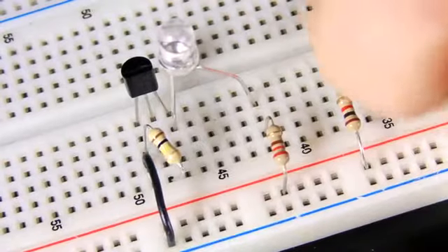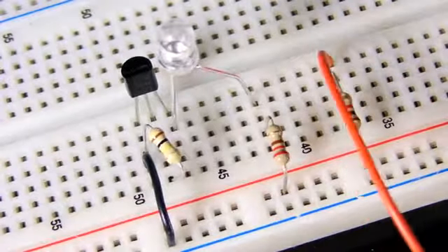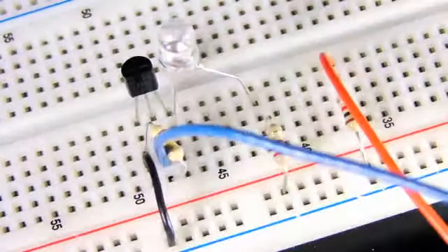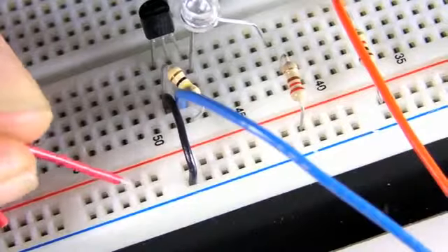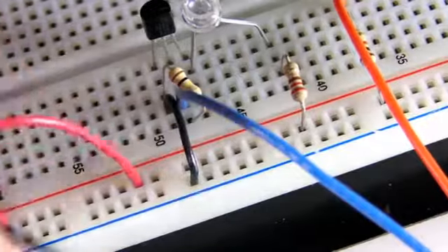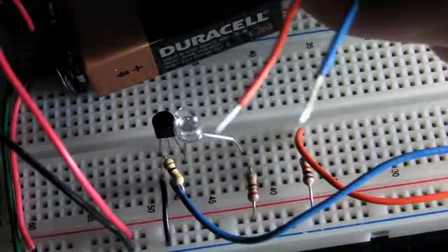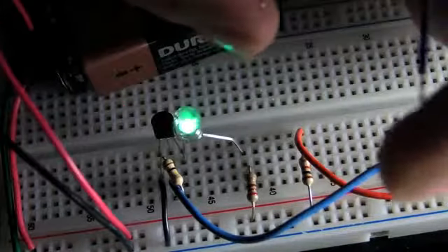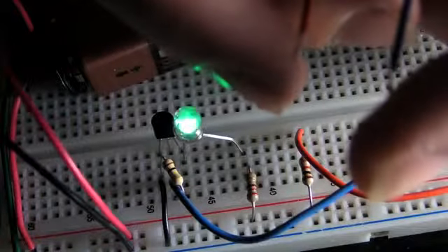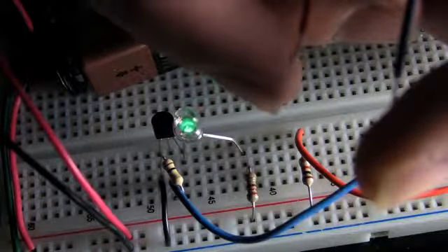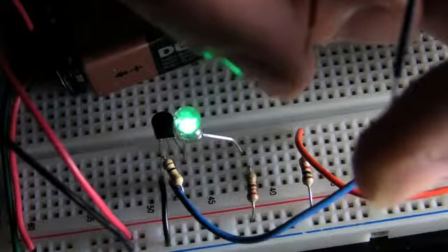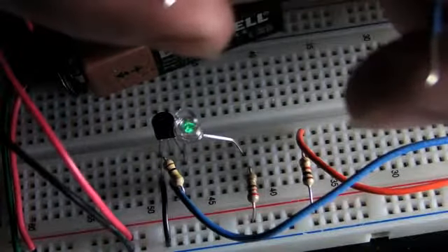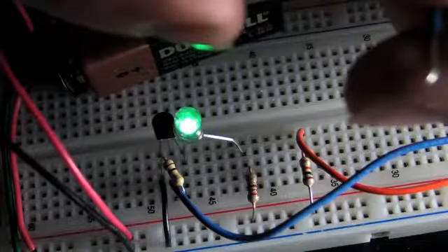Hook up a couple of longer wires to act as your probes. Connect your 9-volt to the breadboard's power rails, and you're good to go. The transistor will amplify the small amount of current present between the 2 leads, and power the LED accordingly. You can use it to measure the resistance of different substances like skin, water, or even a big cookie.